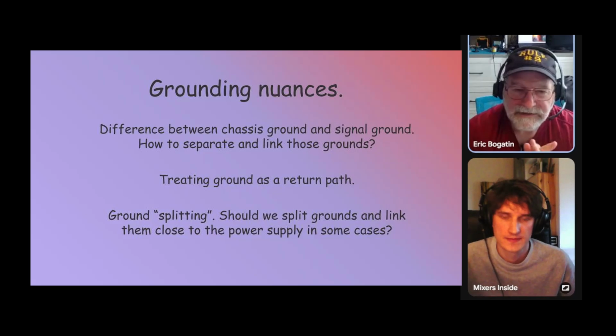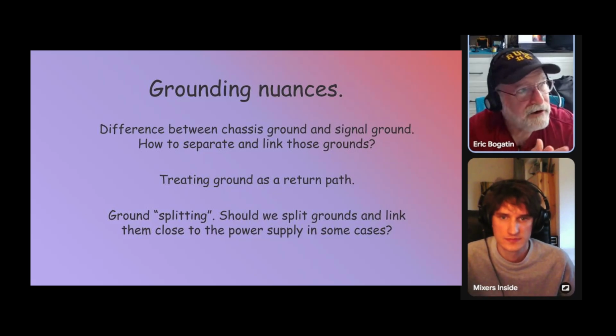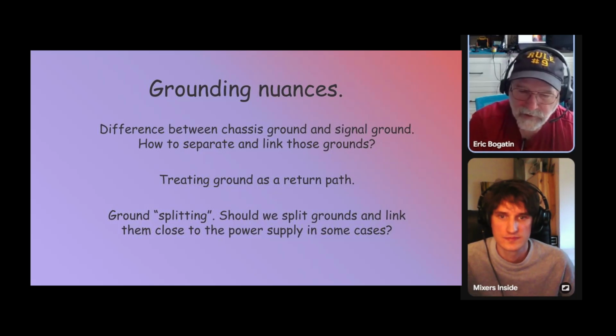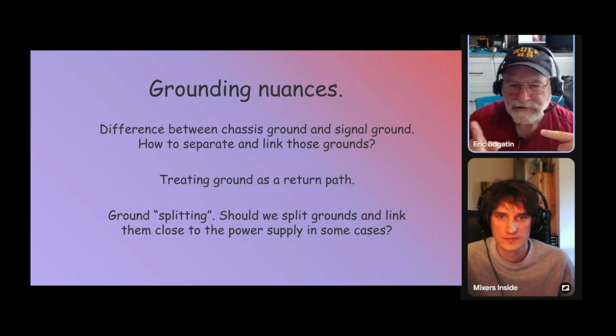We can do it as a split plane. And in the webinar I'm doing in a couple of weeks, I show an example of exactly that. I show a signal line with a wide trace or wide plane underneath it. I have multiple parallel signal lines, about an inch apart, with a wide plane underneath. And I drive a current through one signal line and its return into the plane.